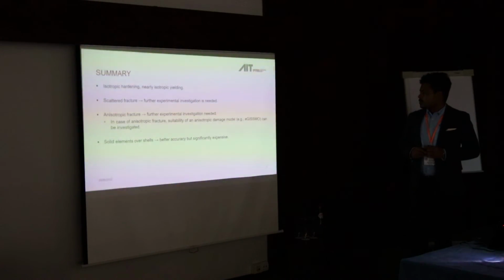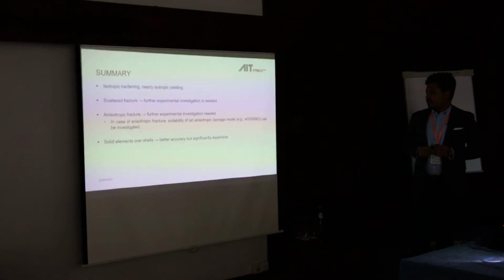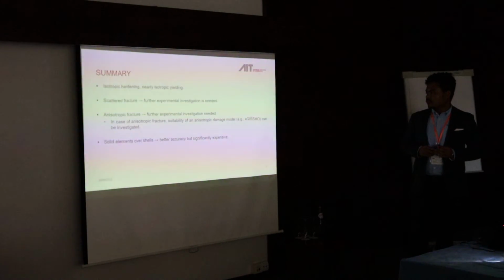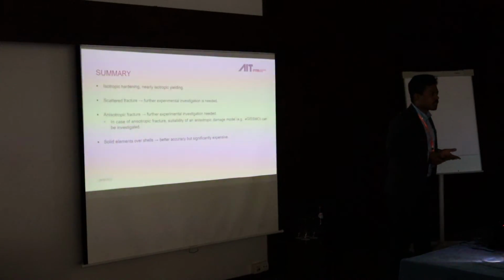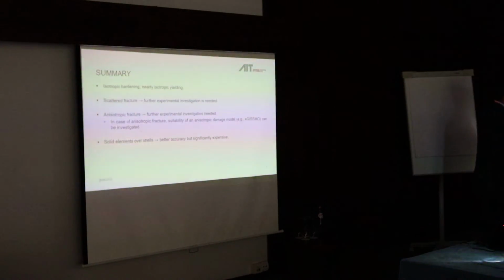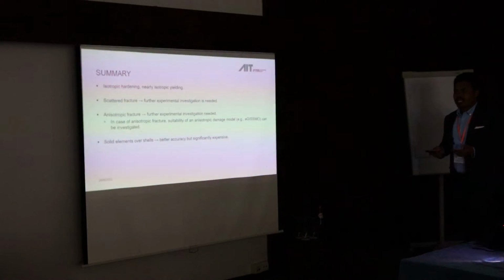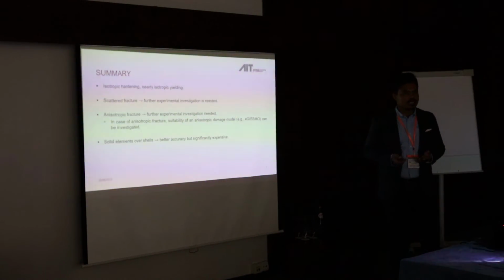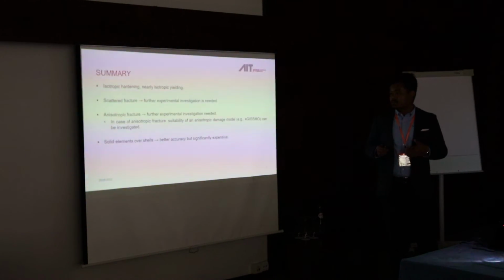so that could be a possible solution. And then I think it's a typical solid versus shell scenario: of course, shell elements for thin-walled structures give us a very fast solution and also fairly accurate. But once in a while we do see that with shell elements we cannot capture the reality. And if we go for solids, then we can mimic the reality better. The question is how much computational effort.